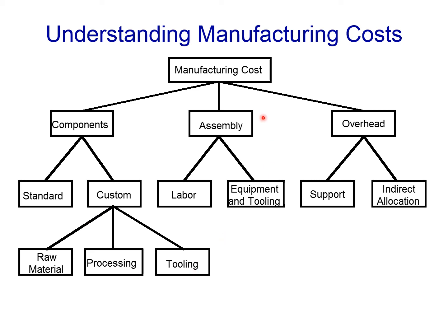Assembly is about 5 to 10% of the total manufacturing cost. But even so, if we focus on how we put the parts together, the savings are not merely due to reducing assembly time by streamlining the assembly process, but also by forcing us to think about reducing the number of parts. The biggest impact of DFM is to do part integration and reduction or reduce the number of parts.